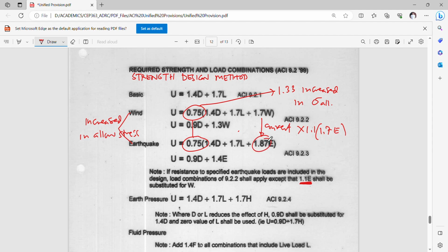So the reason why I'm telling you this is for you to be able to capture the history of how the load factors were adjusted based on probability principles and sometimes also some experts' judgment, but still based on statistical studies they made when they looked into how the forces of wind and earthquake really match the assumptions with that of the actual nature given to us by earthquake and wind histories.